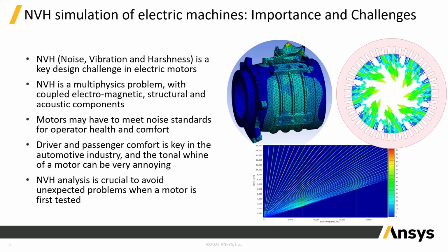We need the right tools that can combine the electromagnetic, structural, and acoustic response to do this effectively. Often the motor's NVH is only analysed late in the design process when the motor's design has already been largely fixed. This gives a great risk that the problem will be found at a point where it's much harder to solve. And what we want to show today is how NVH can be considered from the start of the motor design process, starting with quick and simple calculations and moving into more detail as the design matures.